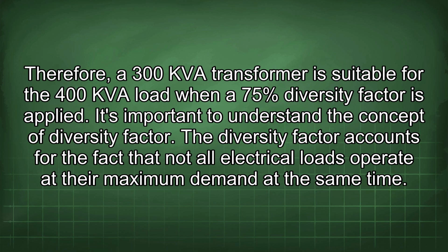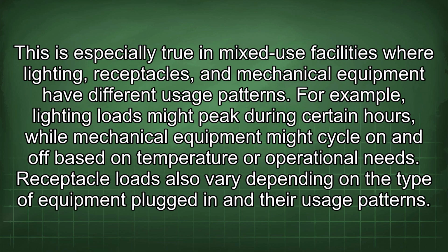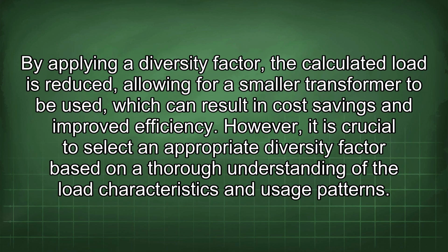It's important to understand the concept of diversity factor. The diversity factor accounts for the fact that not all electrical loads operate at their maximum demand at the same time. This is especially true in mixed-use facilities where lighting, receptacles, and mechanical equipment have different usage patterns. For example, lighting loads might peak during certain hours, while mechanical equipment might cycle on and off based on temperature or operational needs. Receptacle loads also vary depending on the type of equipment plugged in and their usage patterns. By applying a diversity factor, the calculated load is reduced, allowing for a smaller transformer to be used, which can result in cost savings and improved efficiency.